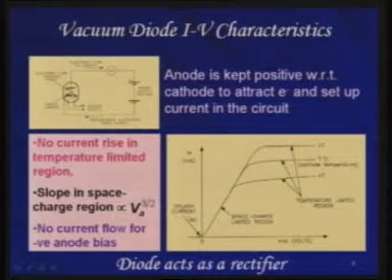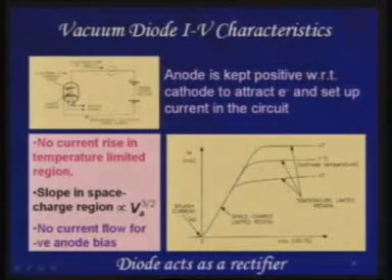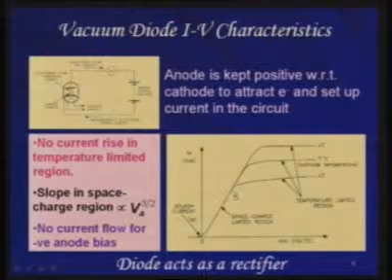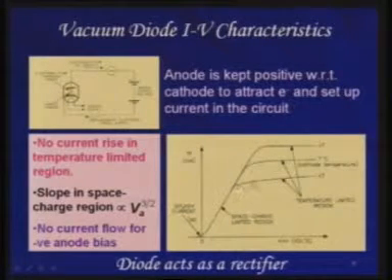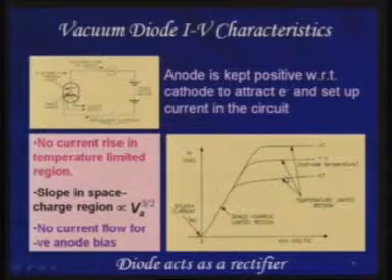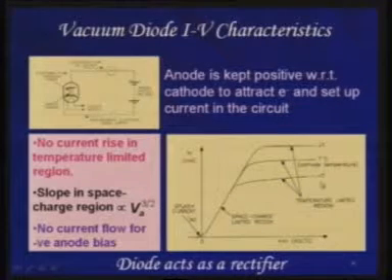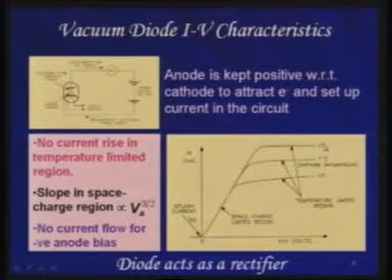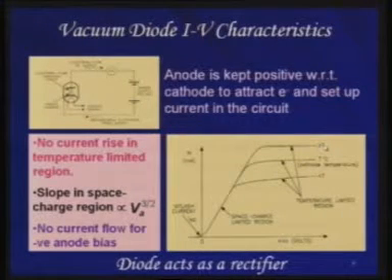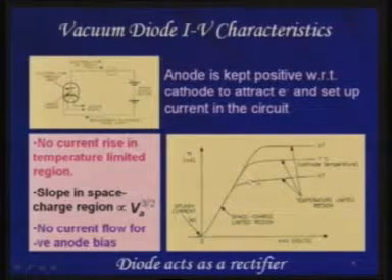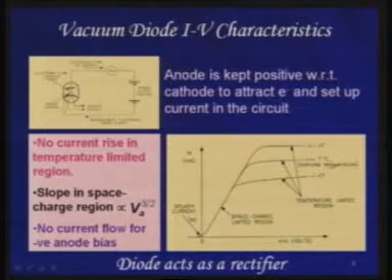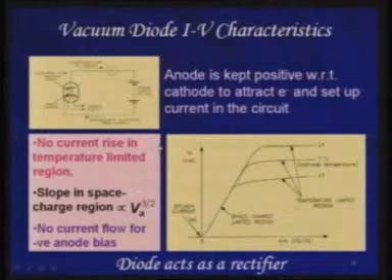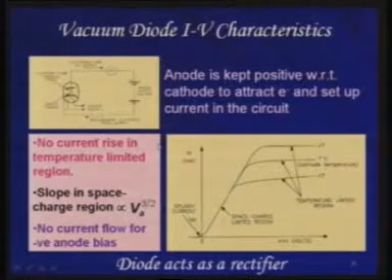So as the temperature is maintained at a certain point, the current that is going to be limited after a certain voltage will be determined by how many electrons are actually ejected at that temperature. If you see, I have drawn here 3 curves, because if you go on increasing the temperature of the cathode, or the filament temperature, then we do get an increase in the anode current, because with higher temperature you get more and more electrons ejected out. So this is what a typical diode is.